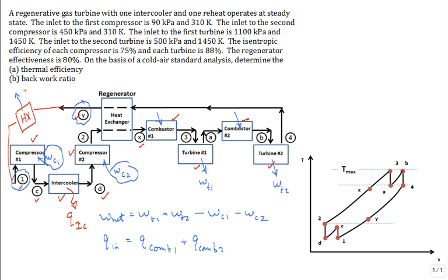And we do have heat transfer out in this other imaginary heat exchanger. But those are the 4 Qs. Did I miss any Qs anywhere? Is there any heat transfer either into or out of the working fluid, out of the cycle or into the cycle in this regenerator? No, it's really in between, from one fluid stream into the other fluid stream.